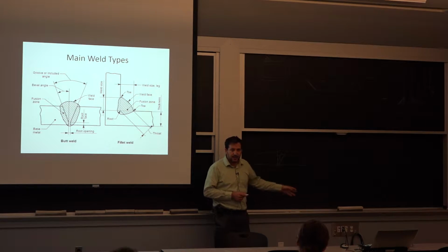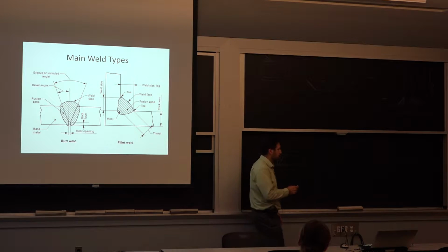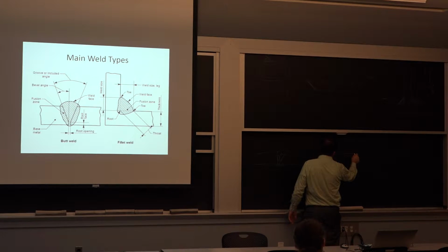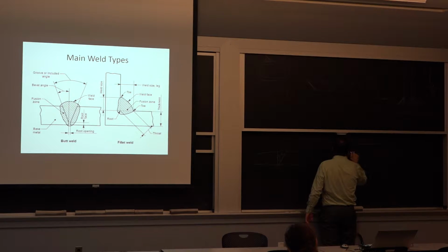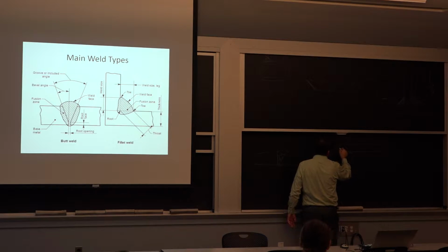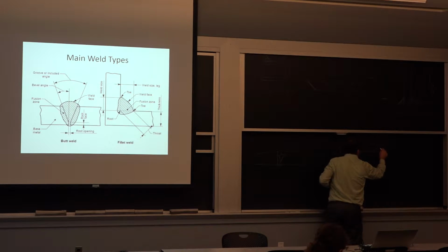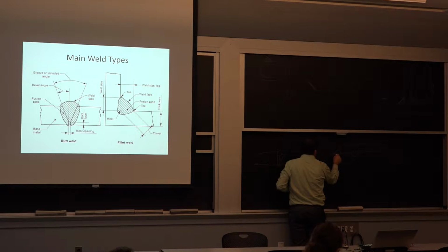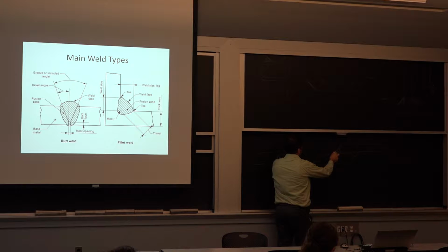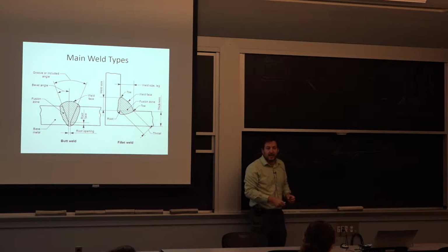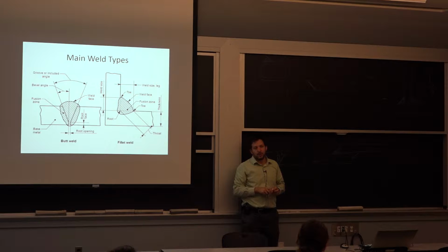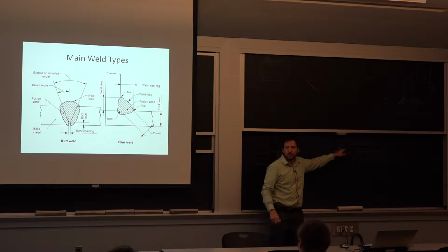And from there, we'll see worse and worse and worse. So, one typical joint that is a little bit more of a problem is, say, I have two members here, but somehow I'm not really able to connect them other than by putting a weld here and putting a weld there. So this is a lap joint, but I made the lap, if my loading direction is this way, so the direction of the weld is perpendicular to my load. That is the weakest type of joint you can have, because now all the load actually carries in tension through the weld.